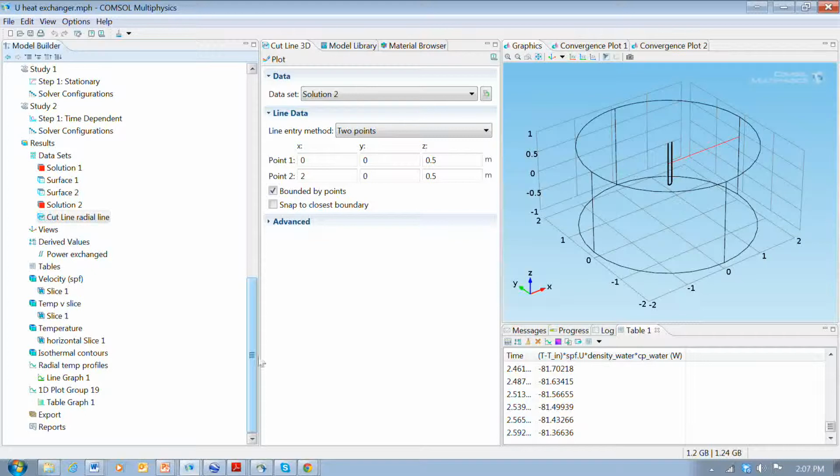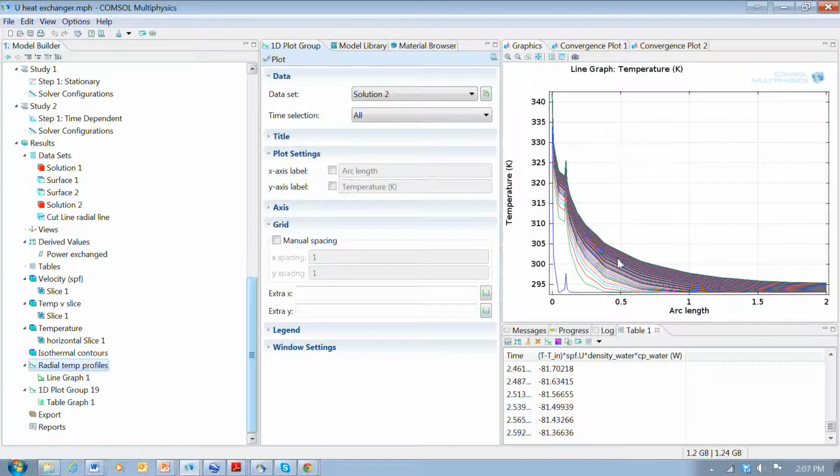And so if we take a look at the temperatures along this profile, they are shown here. We see there's the second tube, so it's much cooler than the first. And then these are the profiles, and you can see they're done at many different times. But at the beginning, the temperature doesn't change out at the boundary. But towards the end of the simulation, it does. So we do have some interaction with the boundary, although it's pretty small. It's only a few degrees change out here at the edge.